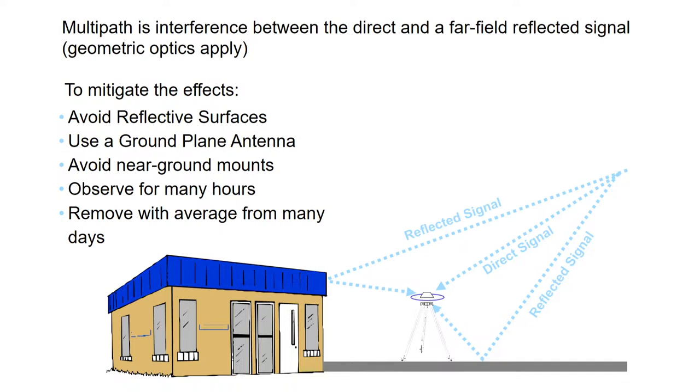Because the signal comes from a low horizon, from a low elevation angle. We know the position of the satellite through two parameters, elevation angle and azimuth angle. The elevation angle we calculate from the base of the antenna, and the azimuth angle we calculate from the north of the earth. When we calculate this, we get the position of the satellite. When the satellite is between 0 and 10 degree elevation angle, it has to travel the maximum distance through the ionosphere, as well as through the various canopy. Then signal loss takes place, and it is called cycle slip.